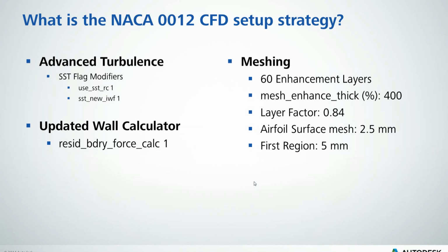Then we start talking about actual setup changes within Simulation CFD. For the most part, we're going to be following our standard advanced turbulence technique that I discussed a few months ago, with some slight changes. As I talked about back then, it's a starting point, and then from there, as you always do with CFD, root it back down in some test data. We're always looking to reduce testing, not eliminate.